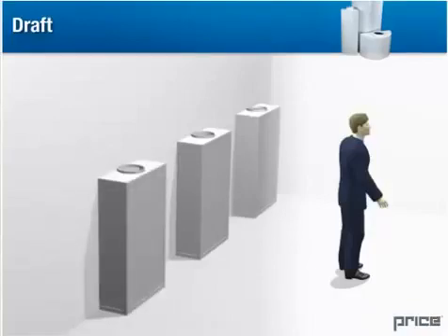By installing more diffusers, the airflow is divided among a greater number of locations and the velocity at each of the diffusers can be decreased. By choosing diffusers with particular airflow patterns, you can carefully position a few bigger ones in unoccupied regions of the room. So where can we use displacement ventilation?